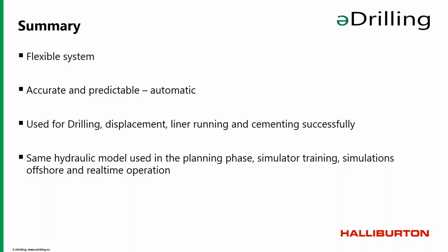And I think also by using simulation tools like we provide here is supporting the knowledge. And I also like to pull through the training part of it, where you have a controlled environment where you can see the effects of adding pressure to the well, opening your chokes, and actually being able to do some errors, but also being able to get some losses and heal the losses by lowering your set point and so on, to actually understand what's happening, and that makes it easier for people to understand.